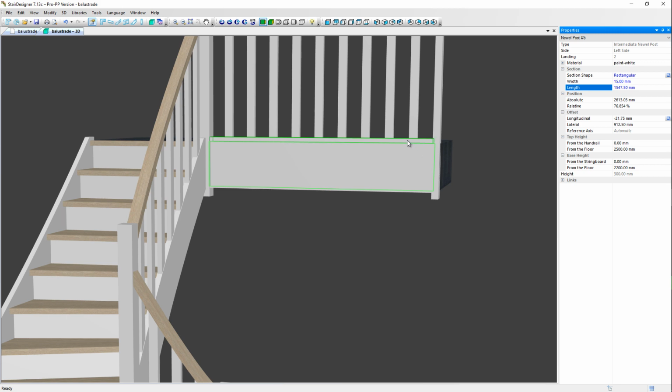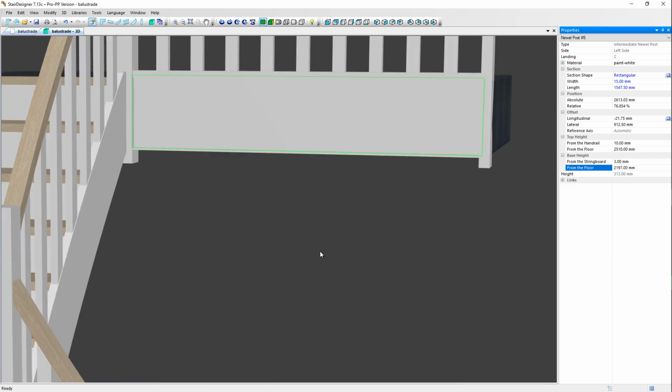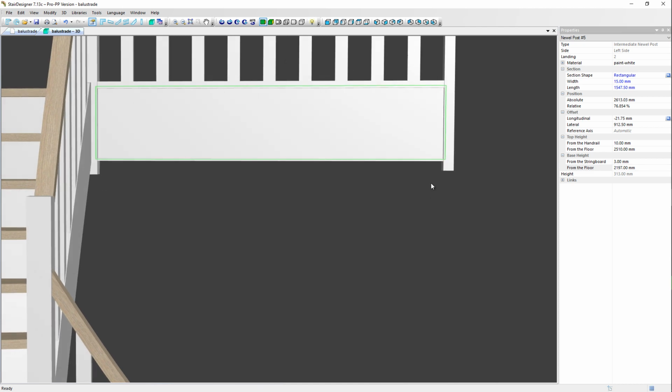To the top side, we will say that we also penetrate 10 millimeter. So the top will be 2510. And the base, we will enter here only a few millimeters, because that's a 10 millimeter. Let's say that we enter this low rail by 3 millimeters. That will be 2197. You see here by the selecting shape that it is penetrating in every item.